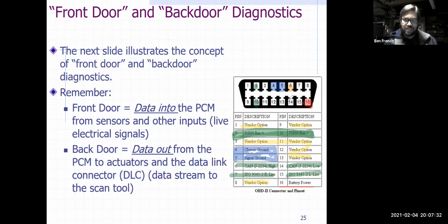So I guess what I'm trying to say is that remember there's different languages spoken between the different vehicles. And so if you had a scanner and it won't communicate, maybe it just doesn't speak that language, right? And if you look at the back of the scanner plug, the DLC is what it's appropriately called, you'll notice that there's not going to be wires going to all 16 of those pins because it varies from car to car on what communication it's going to be using.